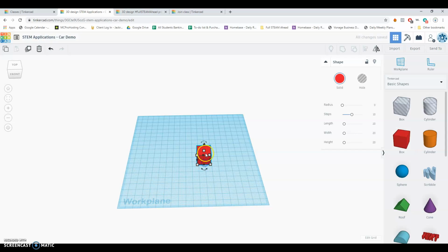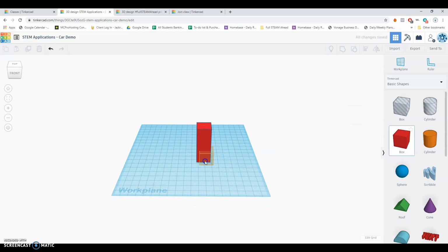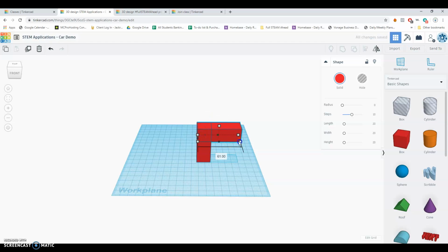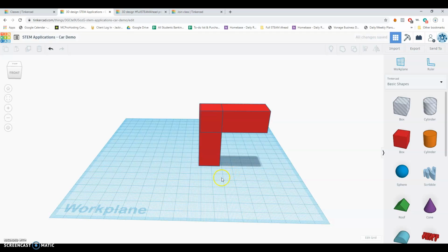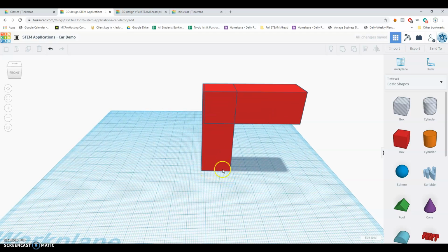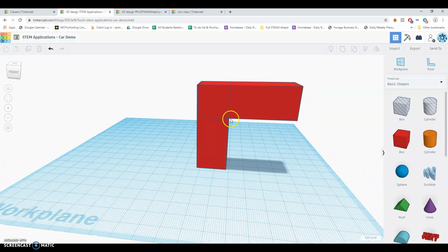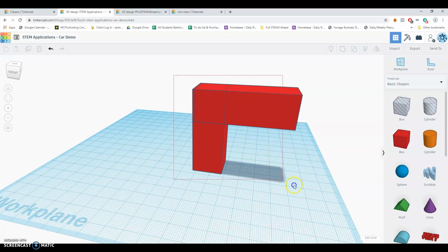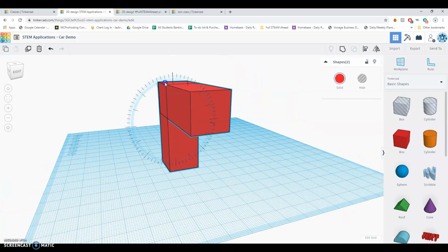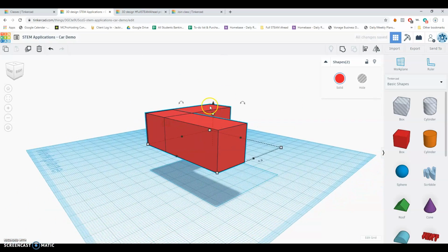If I go to 3D print a shape, something like, let's take this shape. Hold on, a suitably weird shape here. Okay, so if I go to 3D print this shape here, it's going to print from the bottom up, right? It's going to start down here and go layer, layer, layer, all the way up. It's going to run into trouble when it hits right here, because when it goes to do this layer, there's nothing below it for it to rest on, so it's literally just going to droop down, and it probably is just going to get destroyed. Nothing's going to happen over here. So if I were to 3D print this, I would actually be much better off 3D printing it on its side. That way I don't have any of those weird overhangs.